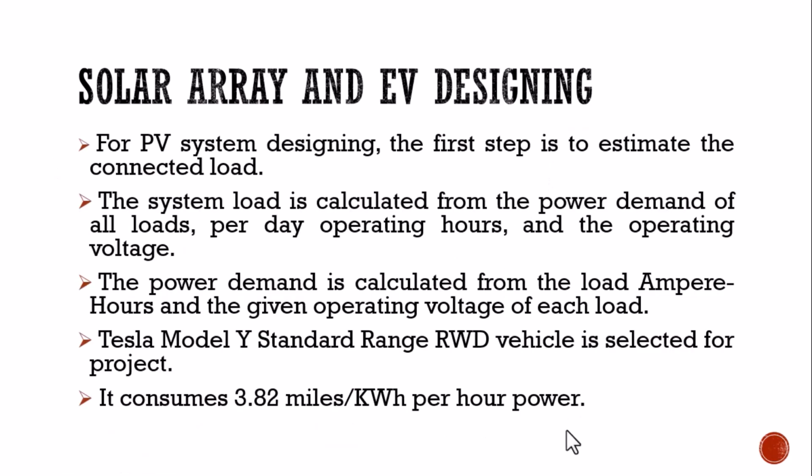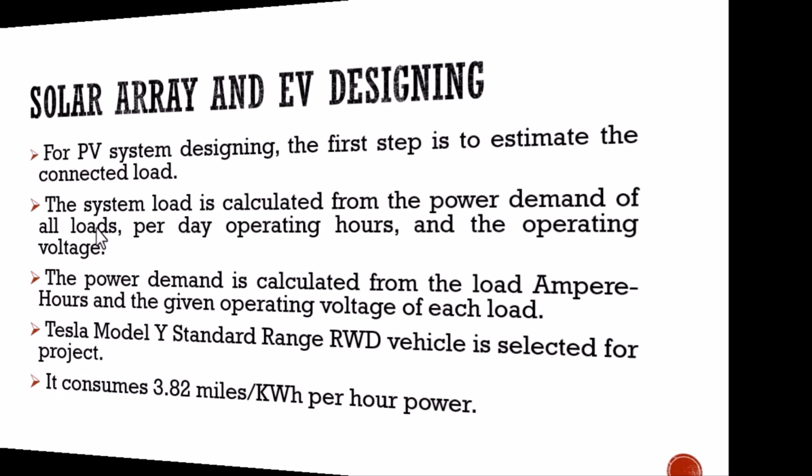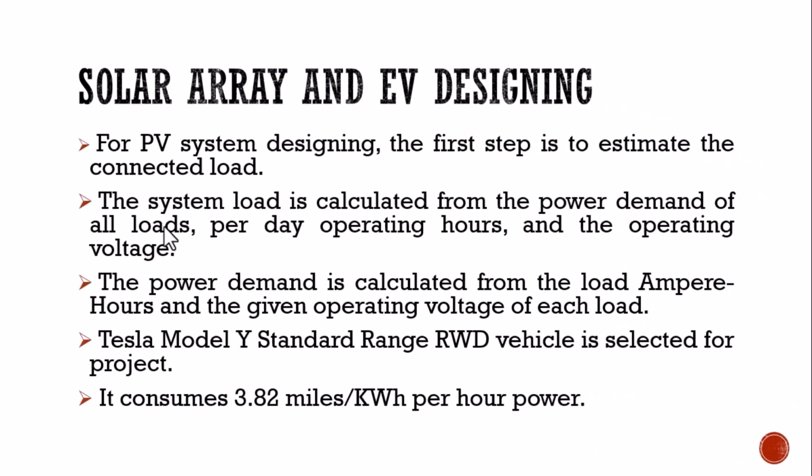Before selecting PV modules or sizing the array, we must determine the total system load that the solar installation is required to support. This includes identifying every electrical load, calculating its power rating, and determining how many hours per day it operates. From these values, we compute the system's daily energy demand in both watt-hours and ampere-hours, based on the operating voltage of the system.